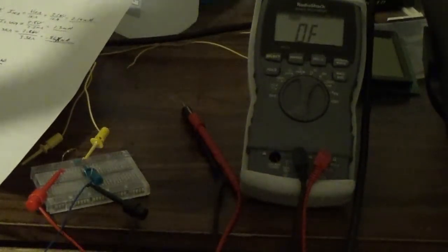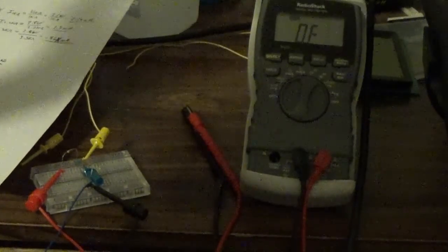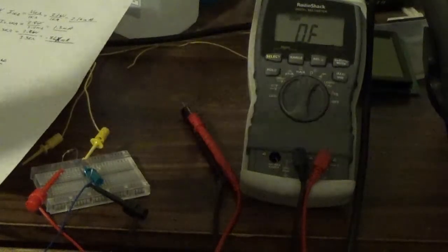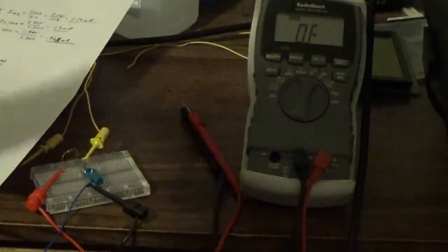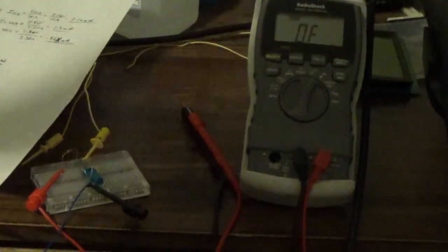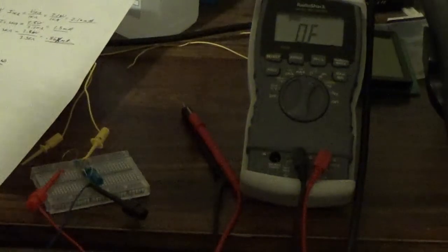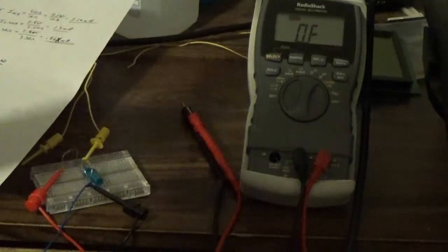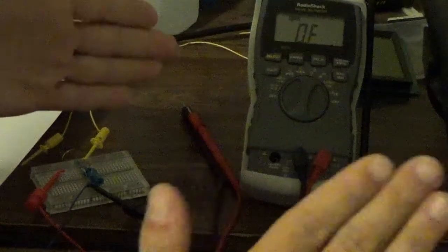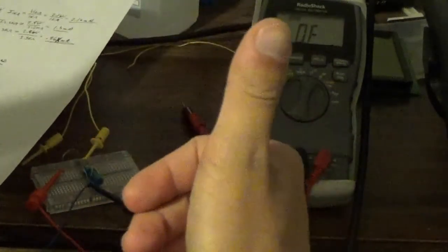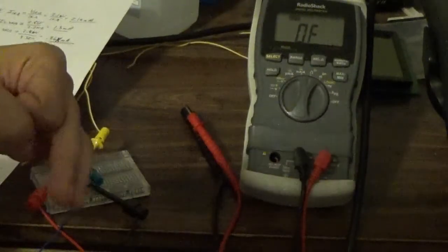Your wall voltage coming out of there is supposed to be 120. Well, depending on the time of day, it could be 110, 105. It can move all over the place. That is a tolerance. Manufacturers have to spec your TVs and your Xboxes and your sound systems to be able to run from a certain range, say maybe 90 volts to 130 volts or 140 volts or something like that. Just in case the load goes down, it has to be able to tolerate the spike in voltage. And if the load goes up, it has to be able to tolerate a drop or reduction in voltage.